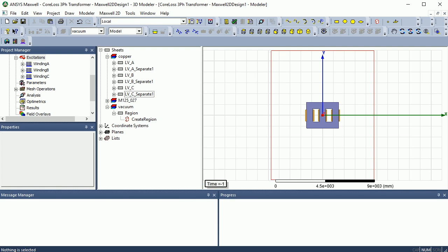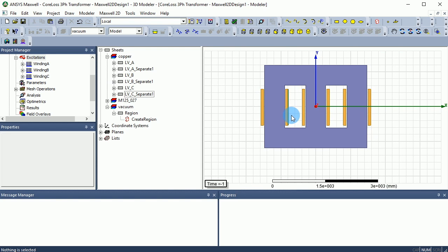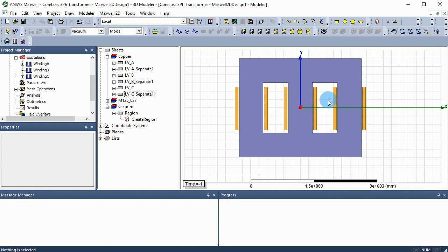This is necessary to make sure that the simulator creates a good mesh for this design. As I said, transient simulation does not have automatic adaptive meshing. For more on that, you can go back to the previous tutorial and see what solutions you have on hand.